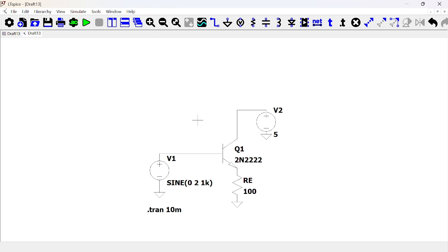This shouldn't be too difficult, but let me just use a voltage source. If I have 5 volts here, I could use voltage division to get the appropriate voltage. What I want is for this device to be always forward active, or forward biased. So I'll start by putting 0.7 there, and we'll see why 0.7 might not be enough.